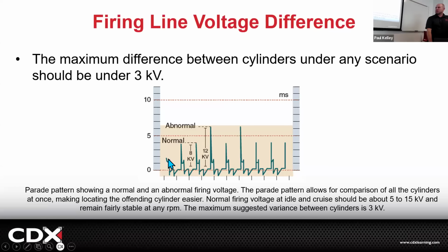What do you notice about this first one? It's low, but what did low mean? Do you remember? Low means high resistance or low resistance? Less. So maybe this has low compression in that cylinder. Or you know what? It just started, so maybe we didn't get the full scale. I don't think we got a full reading on it, but I'm just saying, if this one was in fact low, that would mean that it has low resistance. Maybe that spark plug is fouled or something, right?